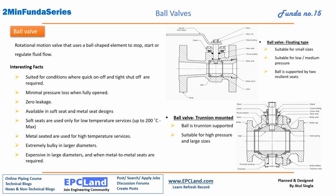The second part is ball valves. So how are these performing? A ball valve is a rotational motion valve that uses a ball shaped element to stop, start or regulate the fluid flow. If you see, we are using the word regulate here. It is stopping and starting, but at the same time regulation is also there. So this ball valve will be part of the second section also, where we are going to discuss regulation valves instead of isolation valves. So what are the interesting facts related to ball valves?